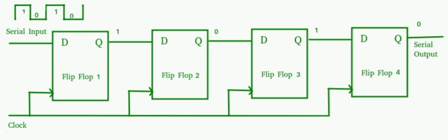Noise margin is the property of a logical circuit to withstand unwanted noise voltage at input, or the maximum value of the noise signal that a system can reject with performance unaffected. VOH greater than VIH greater than VIL greater than VOL. High state noise margin VNH equals VOH min minus VIH min. Low state noise margin VNL equals VIL max minus VOL max.